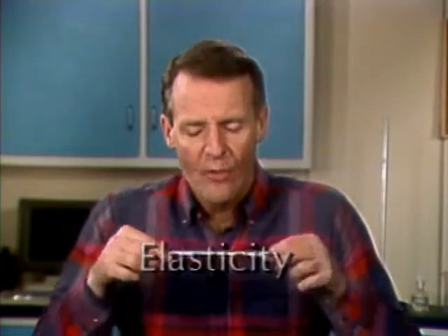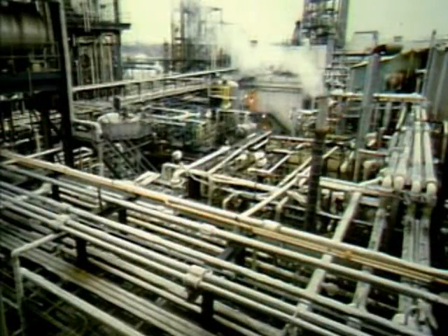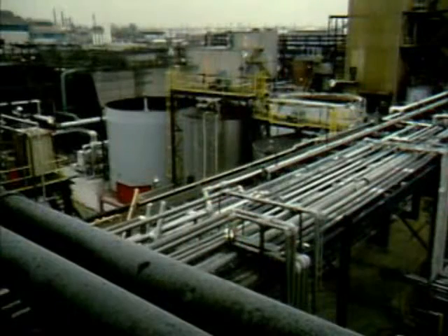A property of many solids is their elasticity. That is, their ability to return to their original shape after being deformed by stress. Piping systems provide a good example of elasticity. Because they're subject to temperature and pressure changes, piping system components often expand and contract. If the pressure of fluid in a pipe increases, the pipe expands, because the increased pressure exerts a force on the inner surface. We've exaggerated the expansion, but even a small amount causes stress. When the pressure is removed, the pipe contracts or returns to its original shape because of its elasticity.